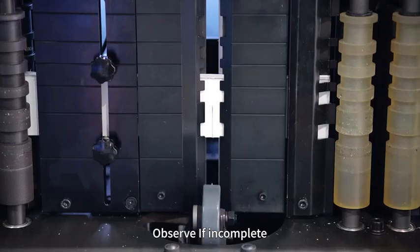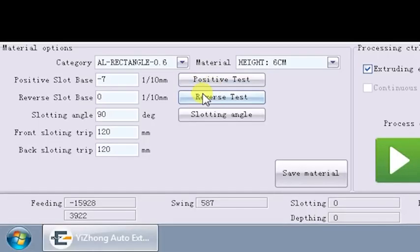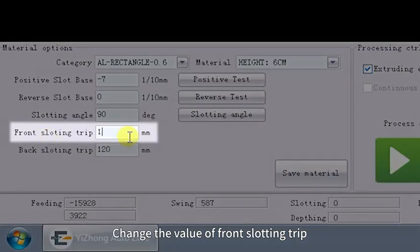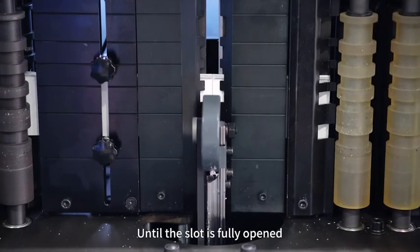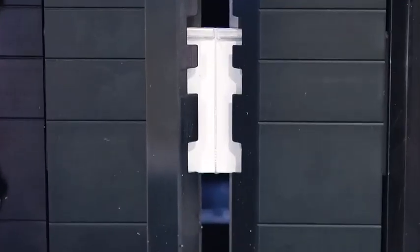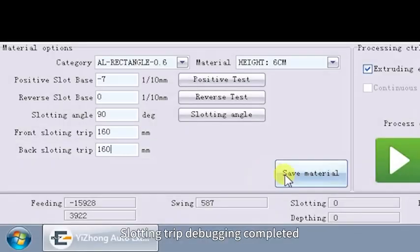Observe and determine if the slot is fully slotted. If incomplete, change the value of front slotting trip. The larger the value, the longer the trip. Repeated testing until the slot is fully opened. Change the back slotting trip to match the front. Click Save Material. Slotting trip debugging completed.